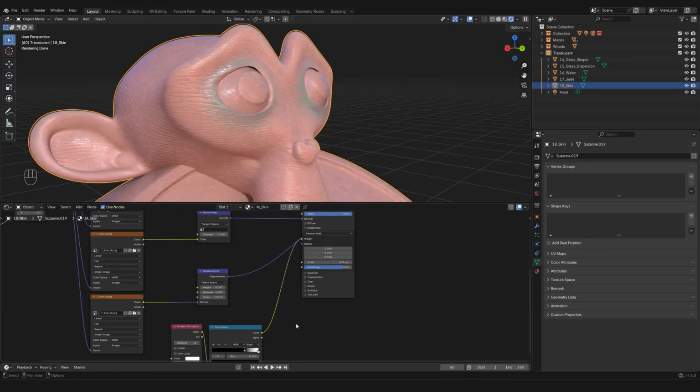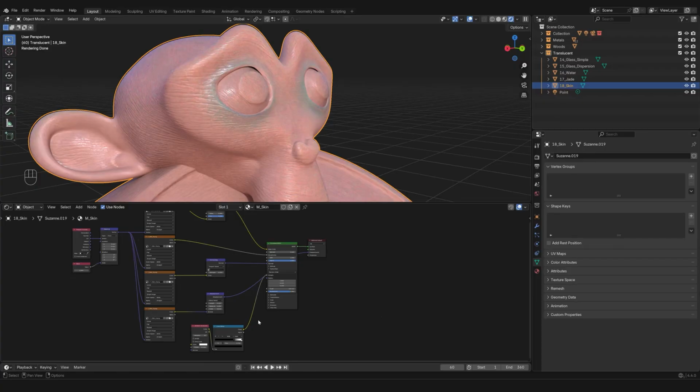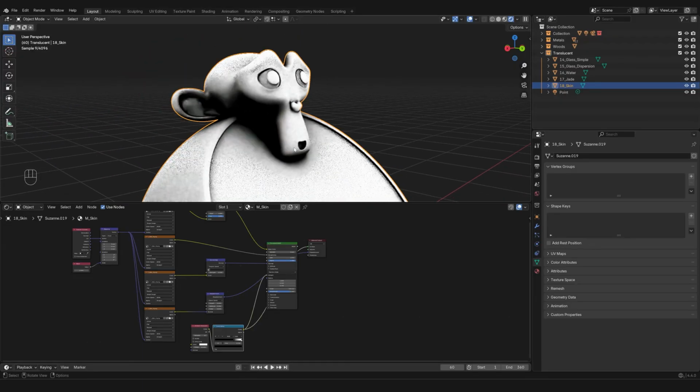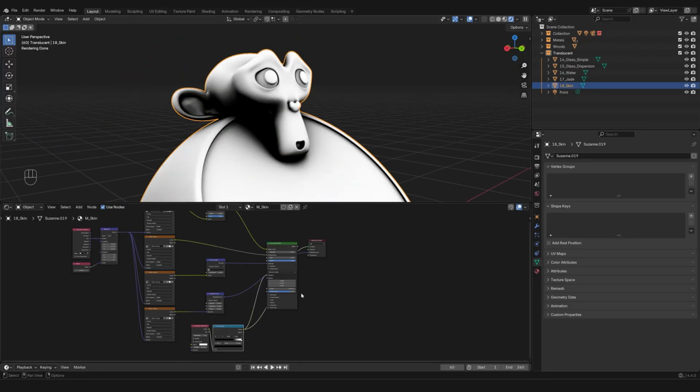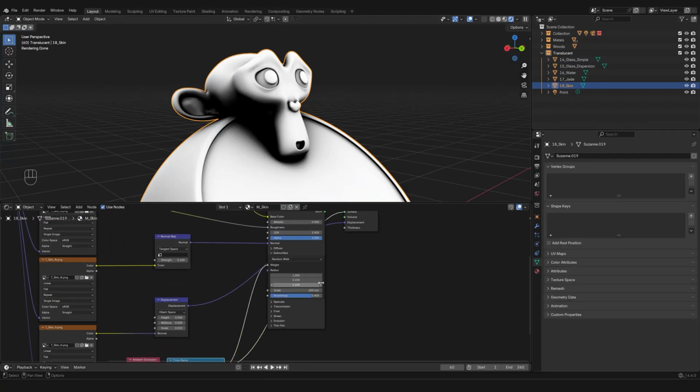And so what I want to show you is that the weight has its own socket, so it follows the same logic and principles of masks. In fact, in more sophisticated characters, you will also have maps that exclude the subsurface effect from happening. So where we have white, the subsurface is happening, and where we have black, the weight is 0, so it is not happening.